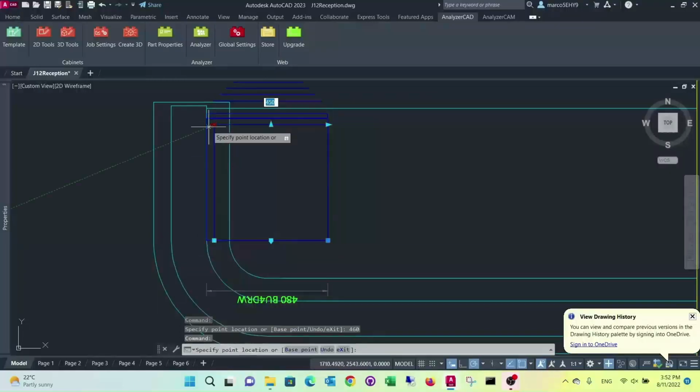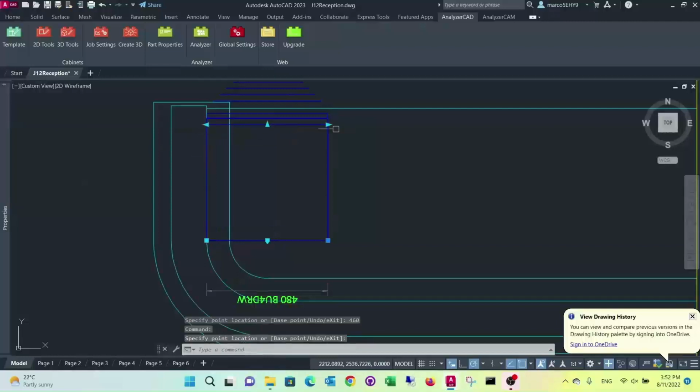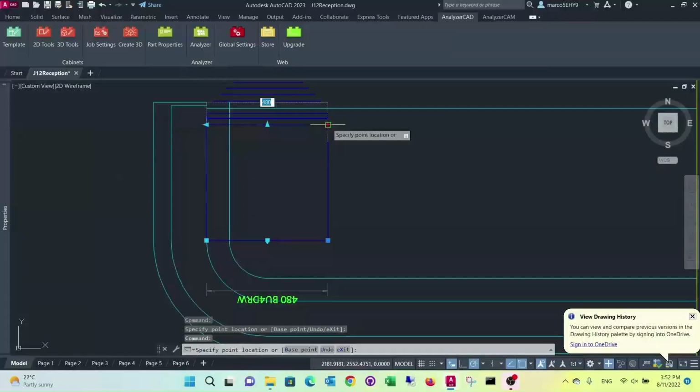We now need to step the plinth back past the seam end by approximately 10 mm. We will make it 470 mm in width.